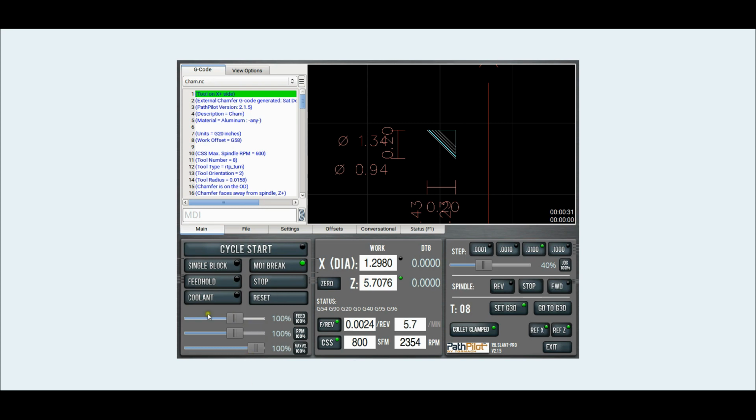These are fun. I use this max velocity one all the time. When I'm running the code for the first time, or I've reset a job up and I'm not 100% sure, I don't want something bad to happen. For instance, I use it a lot to make sure the parting tool parts as close to the collet as I can, giving enough room for a bar pull if I need to. I try to bring it up as close as I can.